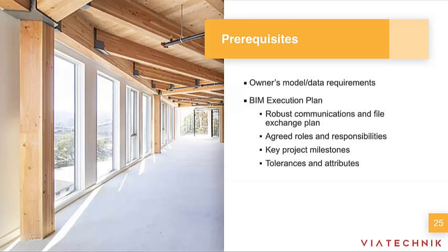With this BIM model, you know, we need to determine who's going to manage it, who's going to maintain it, who's going to be responsible for all this. What, for example, are going to be the naming conventions that are going to be adopted? What construction tolerances are we going to be using? And what attributes are going to be required to be able to use that model later on during the maintenance and operation of the building?